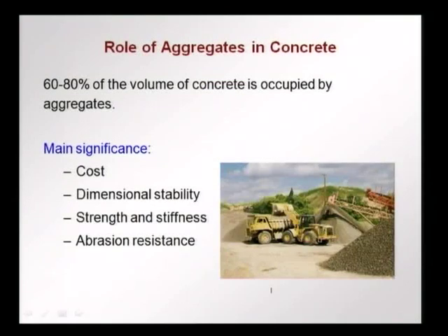Now, a large part of the concrete itself is occupied by aggregates. The cement paste forms only a small part by volume of concrete. 60 to 85% of the volume of concrete is occupied by aggregates or stone pieces. The remaining is basically the cement paste.